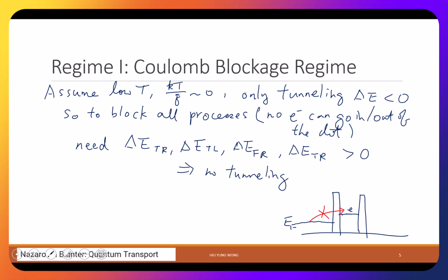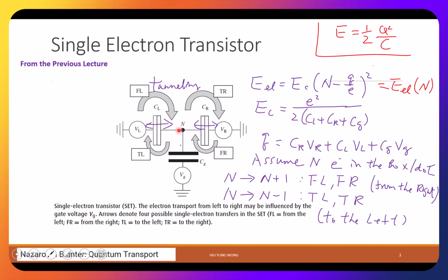So the barrier is in the center. We are not moving the barrier usually, right? You may change the energy of the gates here, the voltage of the gates, and the voltage of the left and right. So you only have 3 gates usually for a single electron device. Just like here.